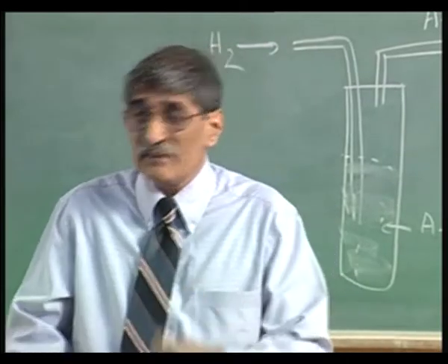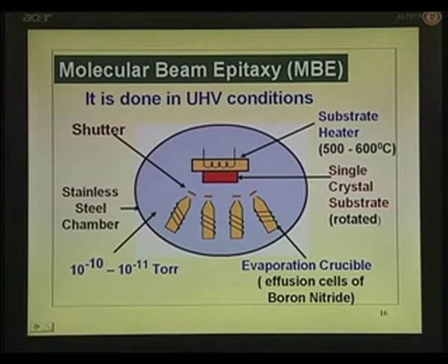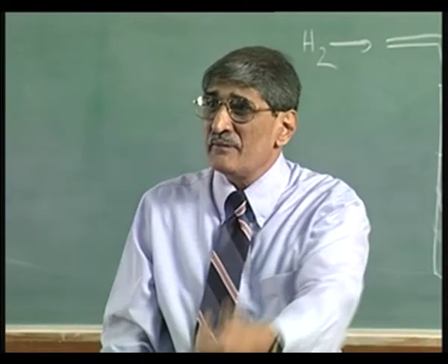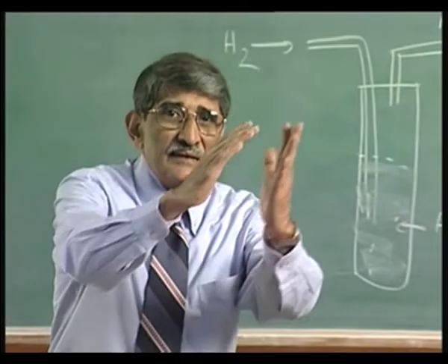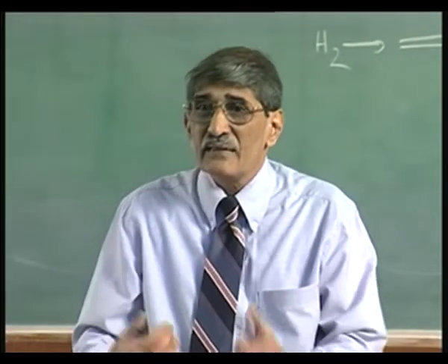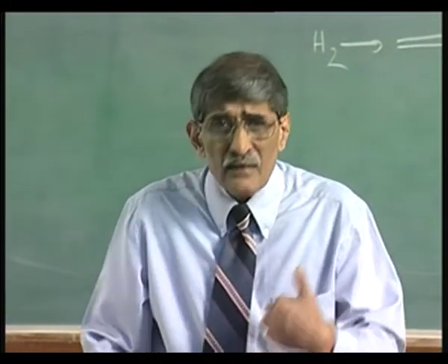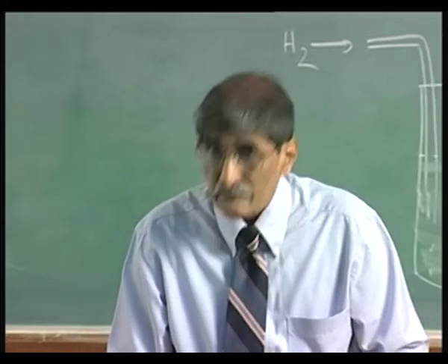Okay, gold gaskets are used between those two. So, those are some of the things that one does to get high vacuum, and the entire process of course is simple. Control the flow of gallium and arsenic by adjusting the temperature, the beams which are coming. You get the beams because of the very high vacuum, that is why you call molecular beam. So, it is coming like that from one beam, another one like that onto the substrate. So, you can get gallium arsenide, very high purity gallium arsenide, 10 to 13, 14, etc.